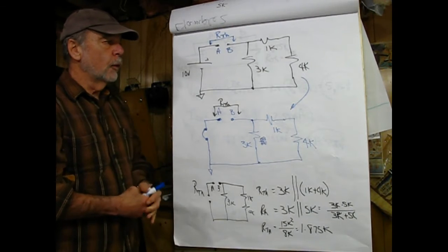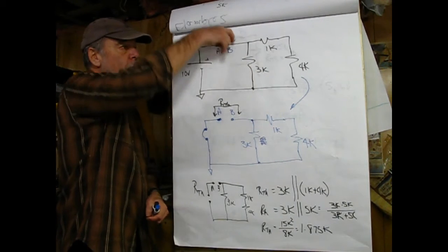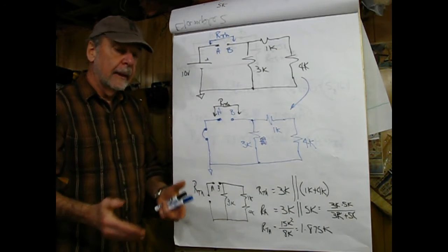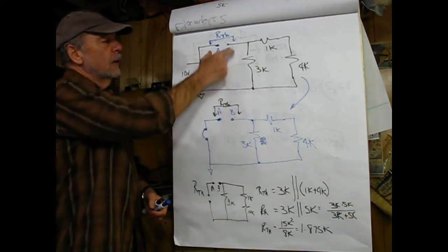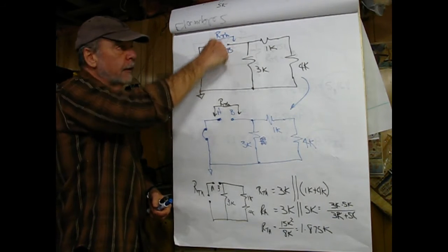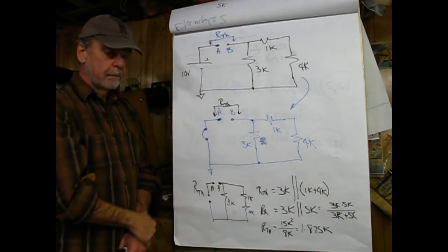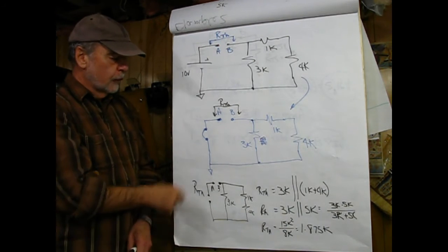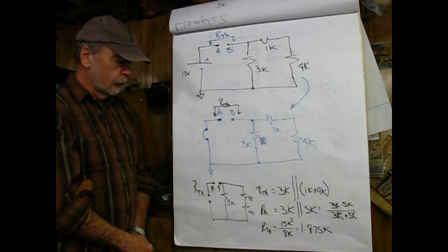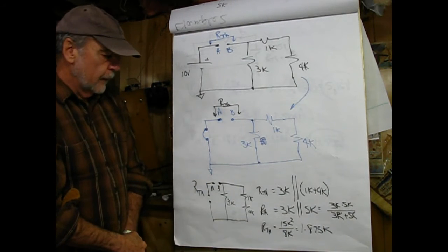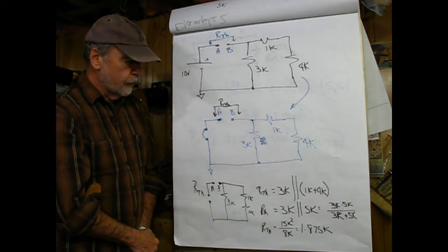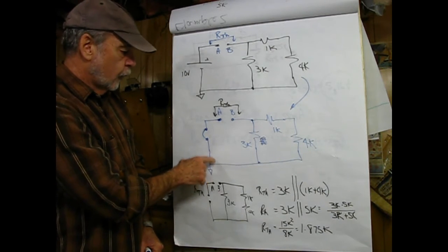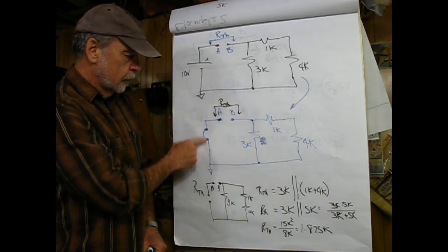And this is super important here. You don't look into this network, you look into this point. Now, this problem is going to be the same. Some problems will not be the same. So, if you remove the resistor here, RTH is looking in from that standpoint. So, once again, I followed the rules. I replaced my voltage source with its internal resistance, which is 0 ohms. And then what I can see from that is, since this is grounded, what I have is RTH